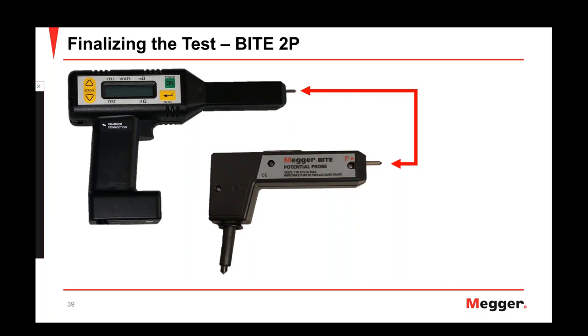What this does is it simulates the strap resistance reading for basically the last strap in the string. This happens because you usually don't have the same number of straps as you do cells. However, if you don't follow this step, the last impedance value that you took for the last cell in the string is not going to be recorded. So it's important that you follow this step.